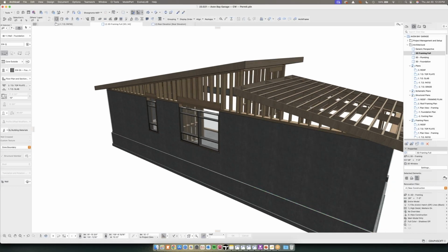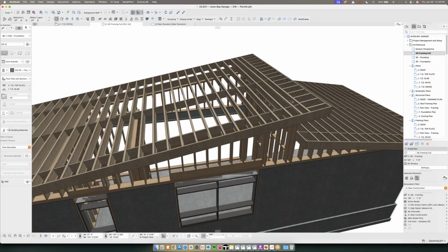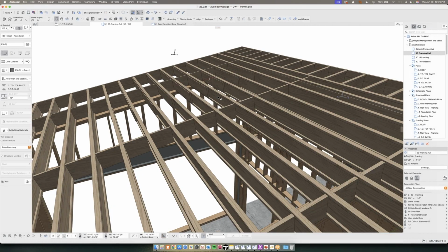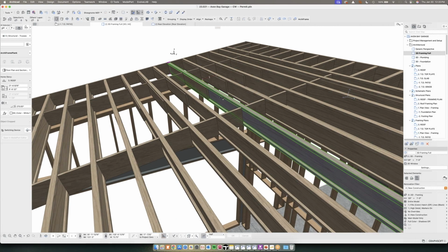But even something where we're doing an unconventional roof framing structure, I have a TJI roof rafter in an unconventional direction with a sistered on 2x10 beside it. So the ability to have this in the 3D model and share it with the contractor through BIMX and walk them through this so they can see it saves me time on the documentation side, as opposed to needing to do 3 different details to show this one element.